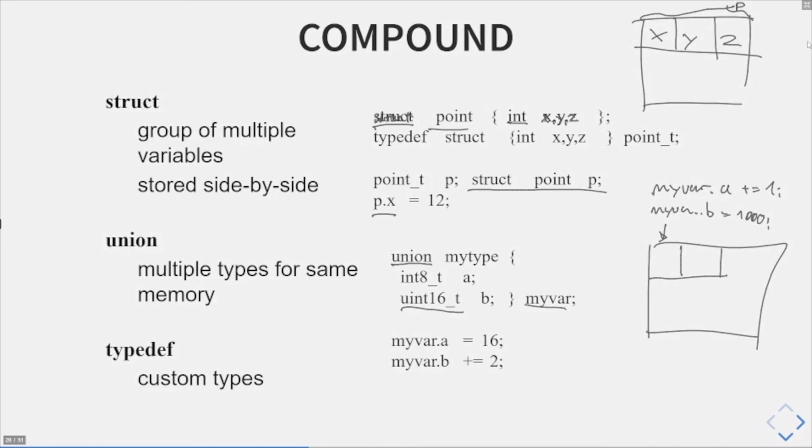And now what you can do is, and we have to look at the other types first, what you can do is to define a union of this sensor value, where you say, okay, the first interpretation of our value is in binary or as a buffer. And this buffer is of an array type, so we can have multiples of those with an unspecified length behind it. This is one interpretation as a character, and then the next interpretation would be as a 16-bit integer, which gives us the temperature as the sensor value.